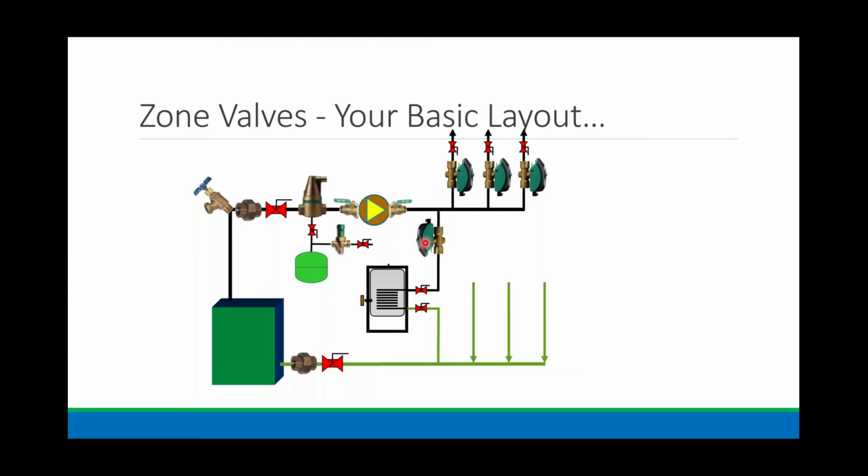Any one of these thermostats calling will energize the zone valve. We'll end up turning on the circulator, and we will fire the boiler. If the aquastat calls here, we energize this zone valve, and we turn on that circulator, we fire the boiler. All right, so that circulator is going to run if any space heating or domestic calls. Okay. How would we wire that up?